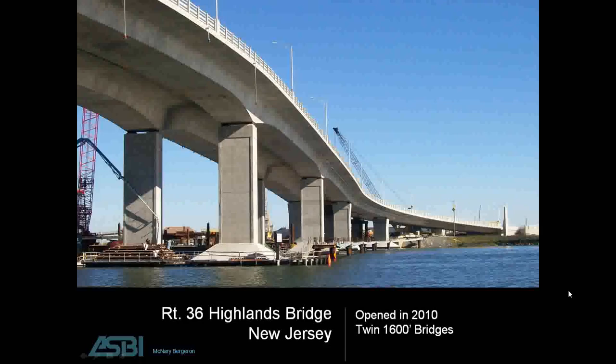I also want to show the Route 36 Highlands Bridge in New Jersey. This bridge opened in 2010, and it's twin 1,600-foot bridges. This is a bridge which has been introduced as precast from the footing up. And the reason for precast was the short construction season. This is a tourist area, and construction had to occur in the off-tourist season, so precasting facilitated that by allowing the precasting to occur all year round, and then the construction could occur in the non-peak periods. The reason for concrete segmental was based on durability. This bridge is in a marine environment, and the owner felt that concrete offered the best solution for durability.